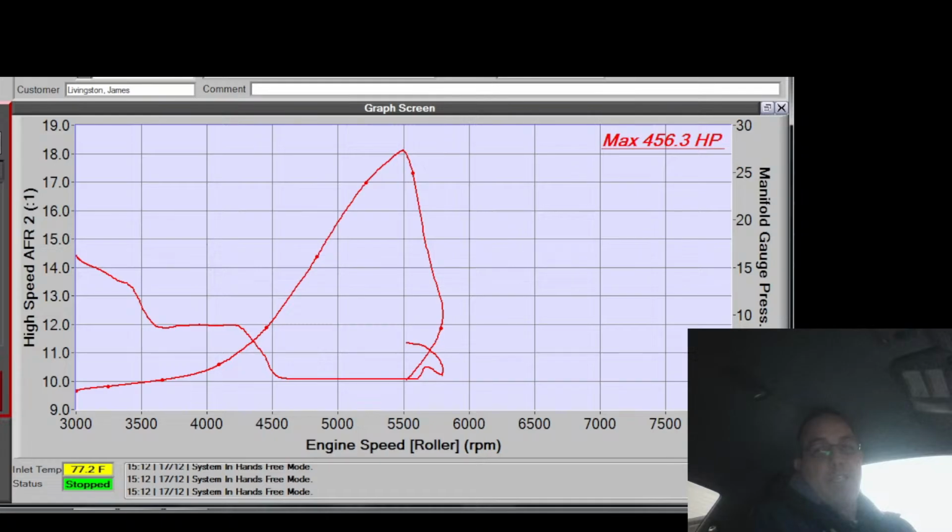It's using the throttle plate movement to initiate an enrichment, because at that point the air is already starting to get into the engine, and the MAP sensor is going to be laggy because it's got smoothing on it. Otherwise your MAP sensor would be jumping around. So you have sensor lag, not just in measurement to reporting time, but in smoothing and stuff in the ECU. So you have to feed it extra pulse.